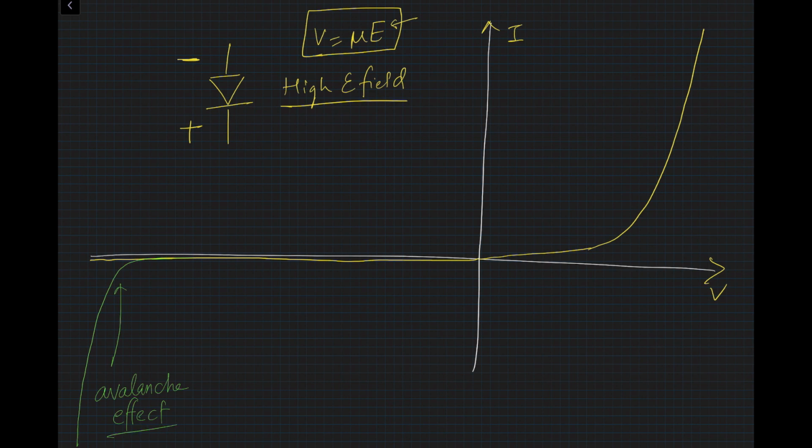Under extreme reverse bias. Okay, so this voltage at which this breakdown happens, this is called V breakdown, is really decided by the doping concentration in our P and N junction. So this voltage V breakdown is high when you have moderate doping concentration for P and N.